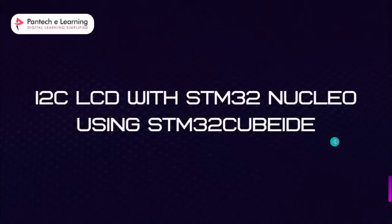So here we are going to talk about I2C LCD with STM32 Nucleo using STM32CubeIDE. In this session we will discuss how to interface an STM32 microcontroller with an I2C LCD module. The LCD module we will use is a Hitachi HD44780 controller based 16 x 2 LCD module with a PCF8574 I2C interface.